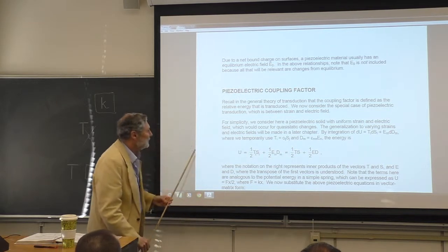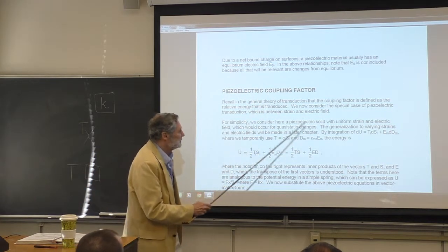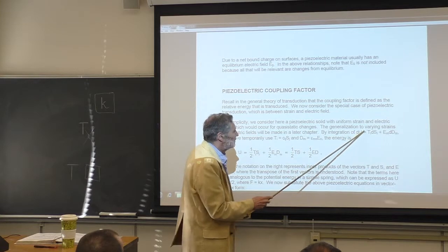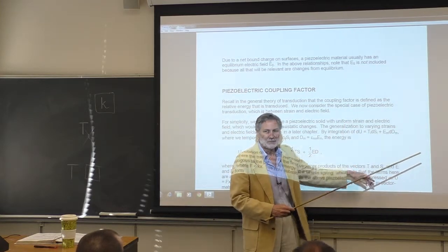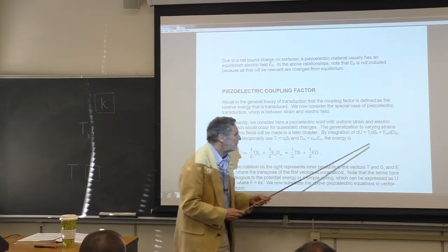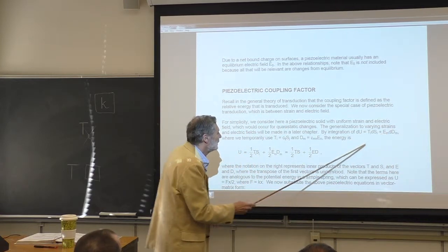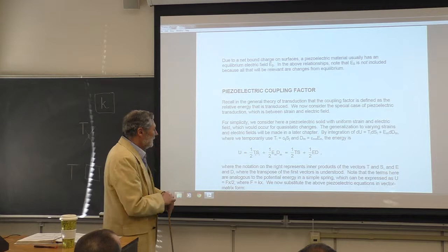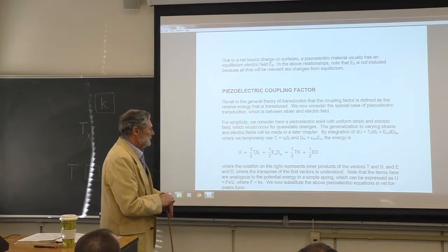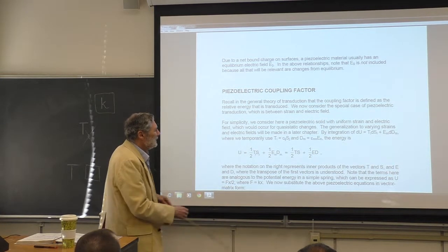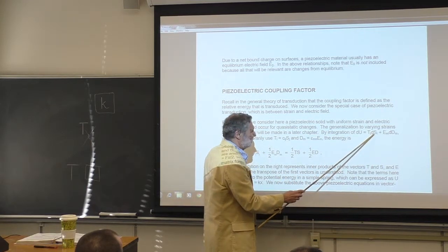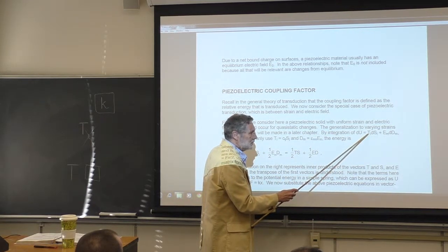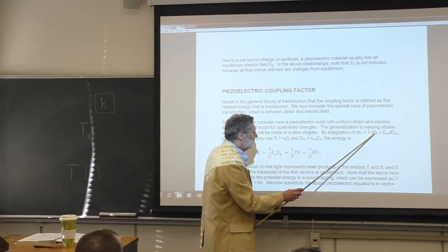And we can do something interesting here to get at this coupling factor. We want to look at the energy. So remember, here's our energy, right? We're neglecting pyro and magneto effects. This is piezoelectric. And we can integrate this. I want to integrate this with respect to S, but the stress is going to depend upon the strain.